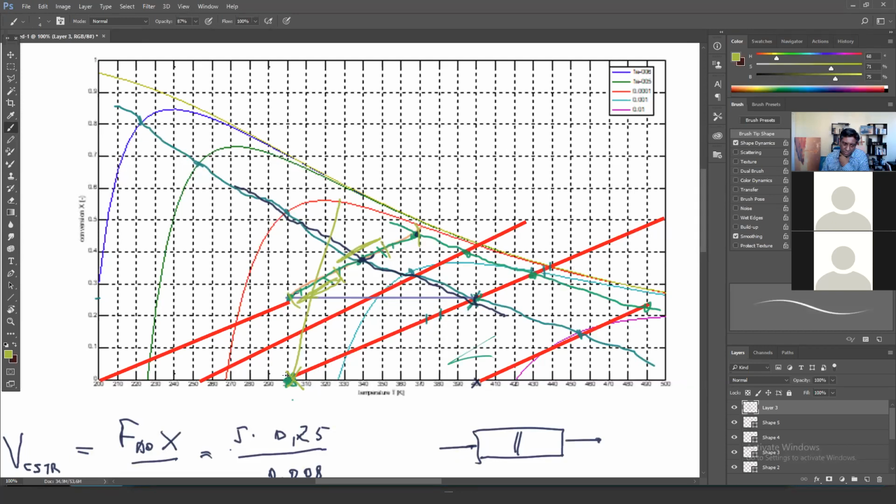So you can say, look, I've got a reactant at 300 Kelvin. The moment I put it in the reactor, my reaction is going to force me to higher temperatures. Instead of loading the whole reactor with the whole stream, let's say I bleed off part of that stream and I send it around the reactor to rejoin. So instead of using interstage cooling, it's like the reverse of recycle. You are jumping over the unit and entering the next unit. So you're feeding the same cold reactant in at one of the future units.